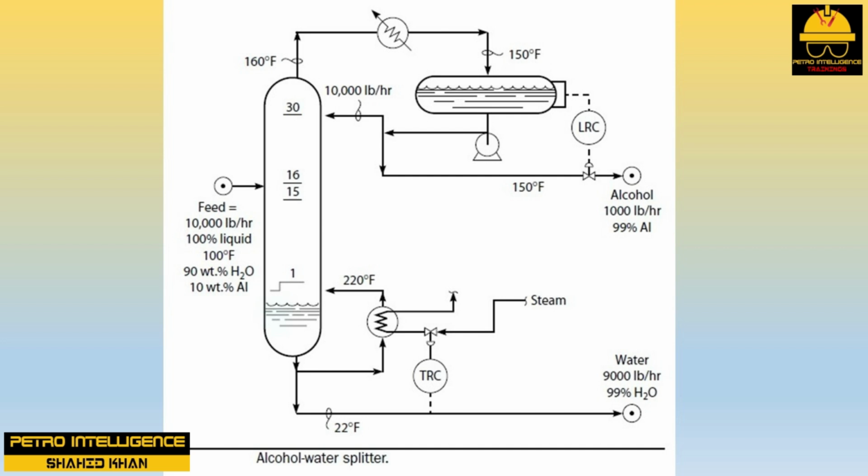We can now draw some conclusions from the foregoing discussion. The flow of vapor leaving the top tray of the tower is equal to the flow of reflux, plus the flow of the alcohol overhead product. The overhead condenser heat removal duty is proportional to the reboiler heat duty. The weight flow of vapor in a tower is controlled by one factor and one factor only, heat.